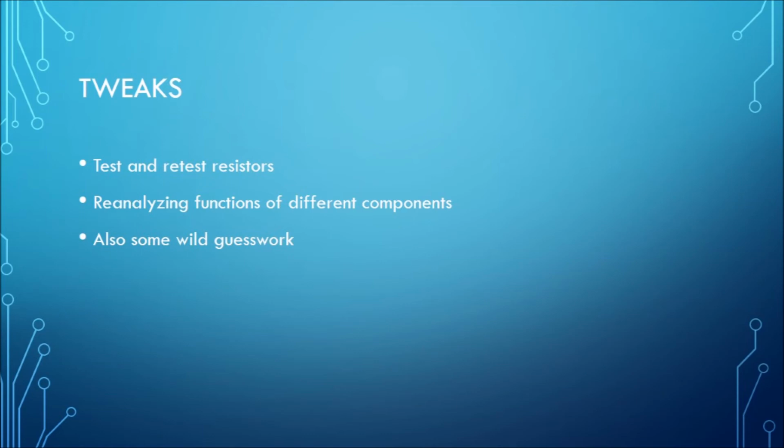This included checking the capacitors as well. But to experiment, we took the bootstrap capacitor out, and the circuit actually seemed to work better without it. Probably because our circuit had open loop gain that was decently around where we wanted it to be, so we didn't have to introduce this feedback in. And in this case, this is actually a pro, because bootstrap capacitors tend to make the system more nonlinear and noisy. So since ours worked fine without it, we decided to keep it that way.